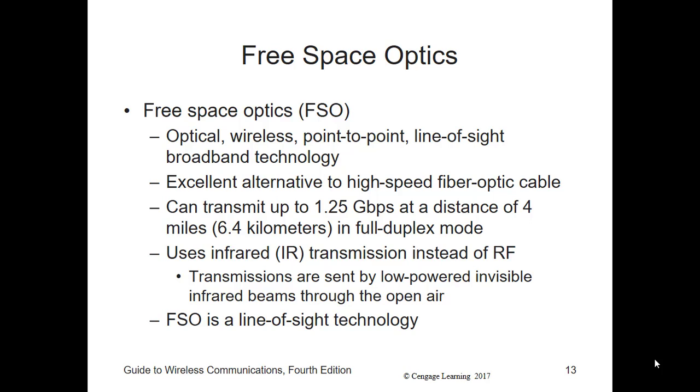It's typically only about as thick as a human hair. Typically going to be 50 micrometers for multi-mode, sometimes 62.5 if you have an older multi-mode fiber. And you're looking at 4 to 8 micrometers for single mode fiber. So that's as thin as a human hair.